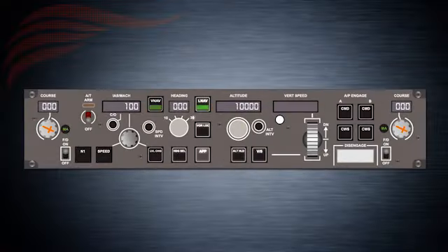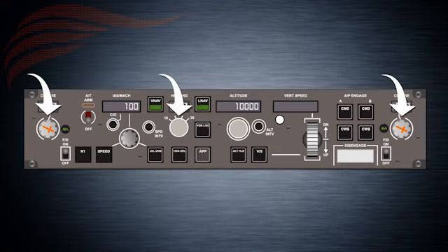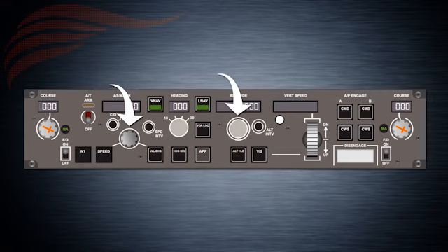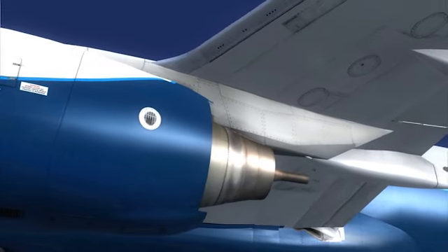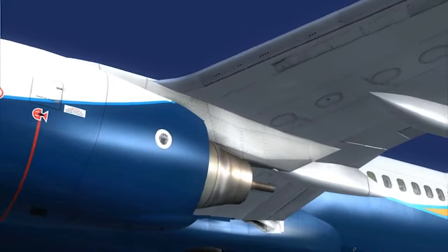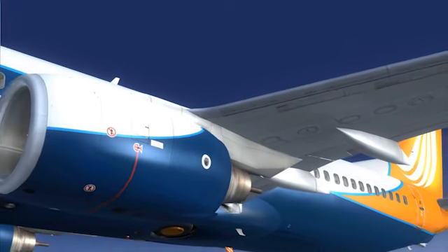Some of the functions of the MCP, to name an important minority, are engagement of the autopilots, turning on the flight directors, selecting the mode of operation, arming autothrottle, selecting course and heading, and selecting target speeds and altitude. Now, it's actually not that simple and easy when it comes to the MCP. There will be much more to come as we're flying later, as mentioned many times during this lesson.